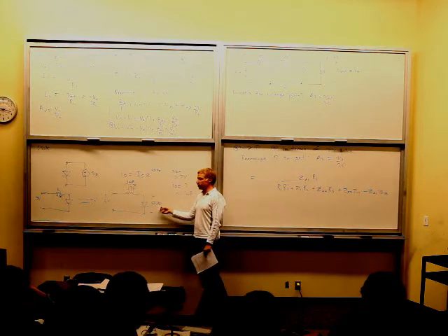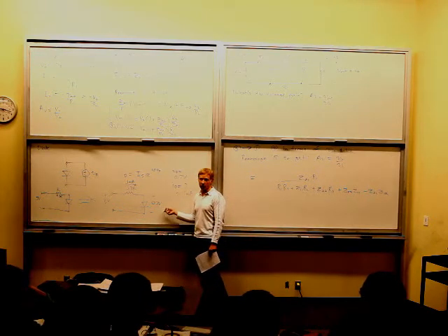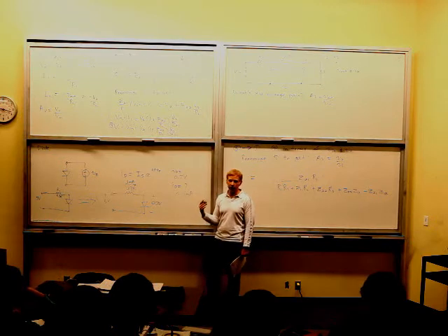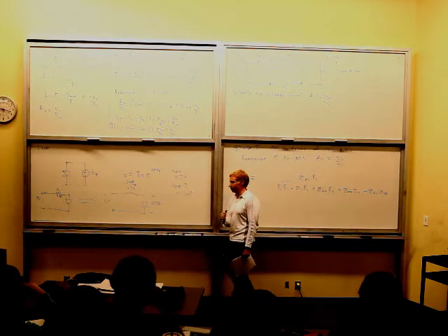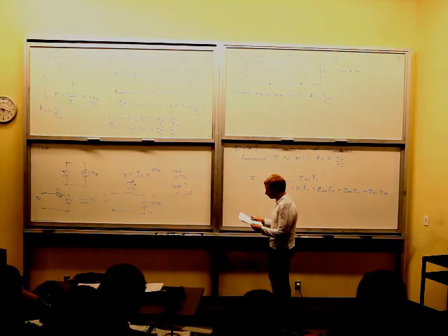So for diodes, for BJTs, just bias it at 0.7 volts and go. Unless it specifically says use an iterative method to find the exact DC operating point, which I think would be a poor use of testing your knowledge of this course. I'll leave it at that.